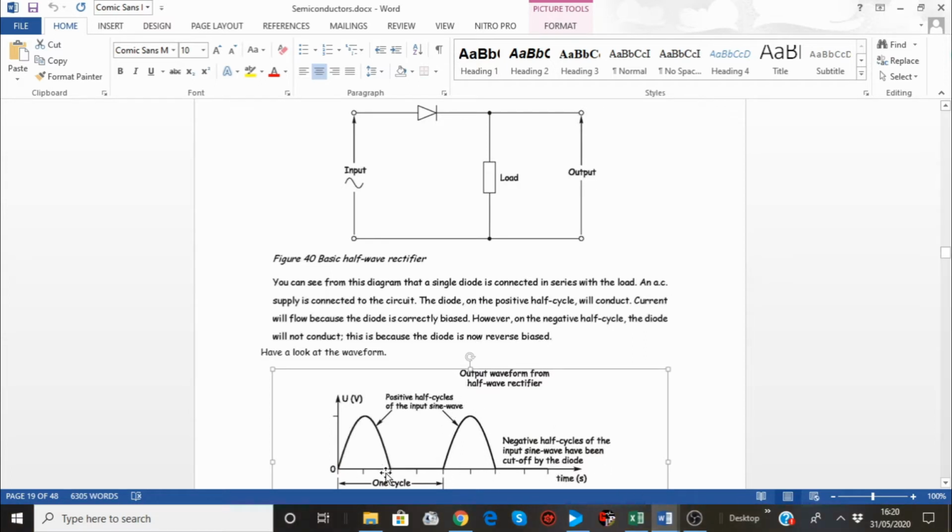Keep doing that. So you'll have bumps with gaps in between them. And that is called half wave rectification, because you're only rectifying half a wave and you're losing half. This is turning the AC to DC, well, it's not a very good DC.